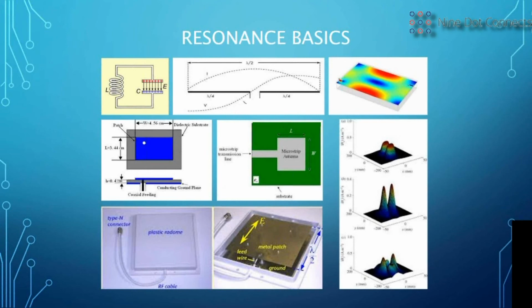And you can see that in the red areas there's a lot of motion on the sides of the plate and almost no motion in the very center for this mode. If you look directly below that, there are plots. In one going between the narrow faces, you'll see there are two humps of energy, based on the frequency of excitation. If you go to the next plot down, you're seeing that it's being excited in the long dimension, and you also get two humps. If you excite it otherwise, shown at the bottom, you get a combination of those.